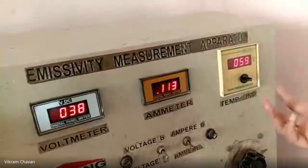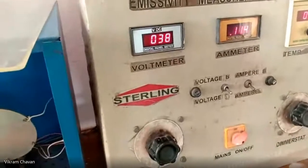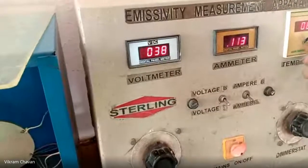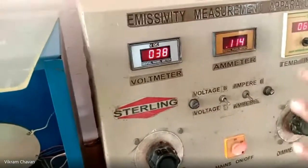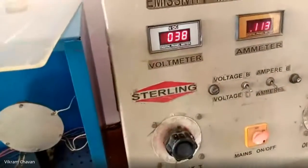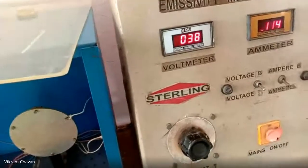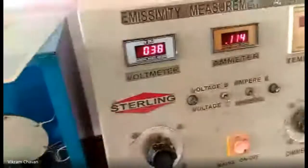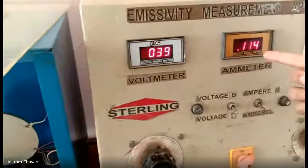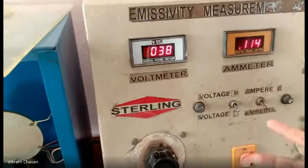Trial and error is required to find at what voltage you get the equilibrium. Now we are getting the readings for V1, V2, I1, I2, and T1, T2. The two temperatures are equal, so then we can take the voltage readings: 38 and 0.113.